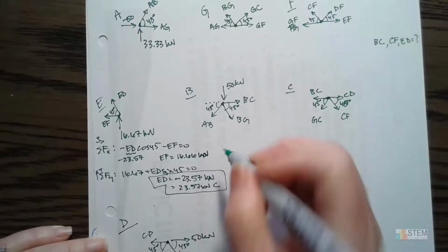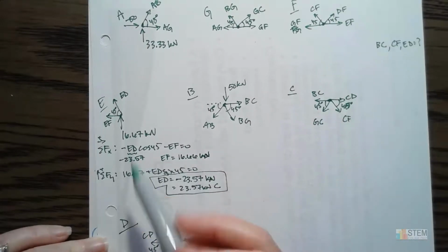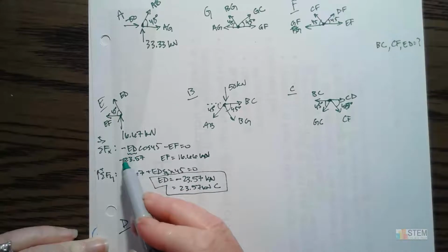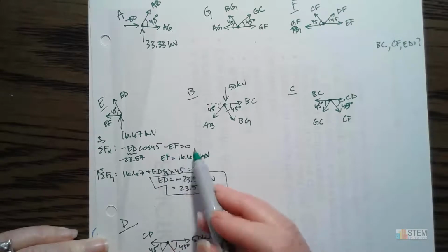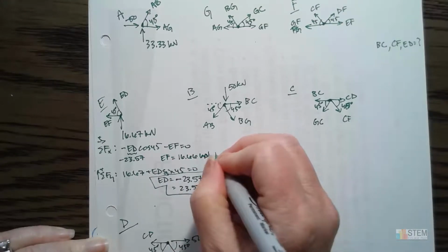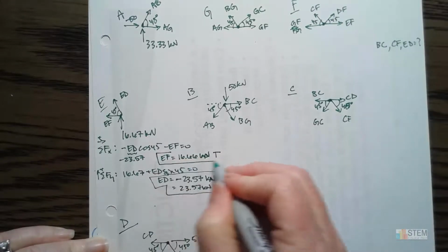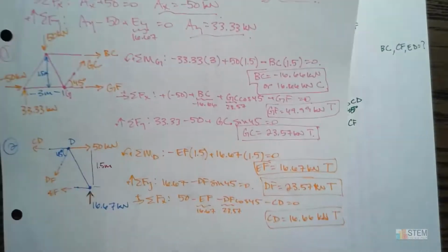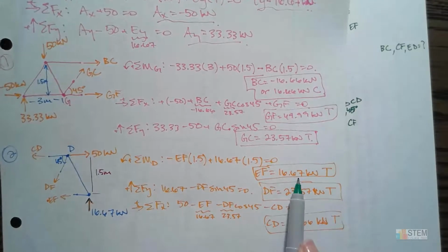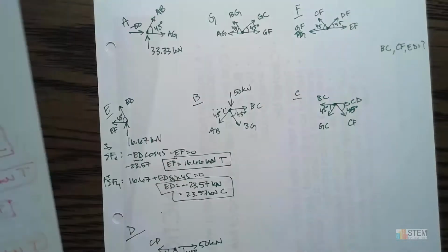Now, if we look at our signs, we got a negative times a negative, so that's positive, right? Then when I move it over, it becomes negative. We divide through by this negative, it becomes positive. So it's positive, so we get a tension there. And if you look at the page we had before, that's exactly what we got here, right? So same thing.